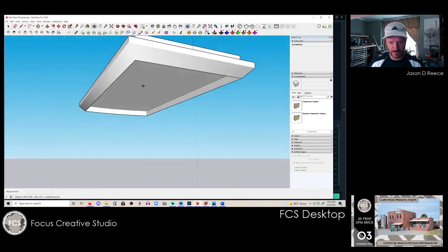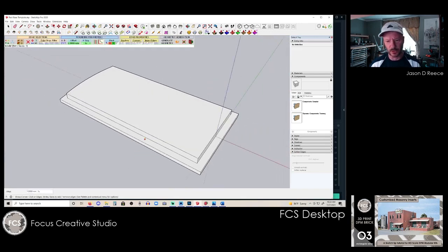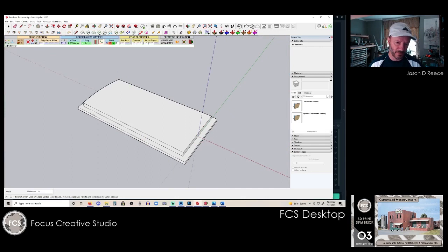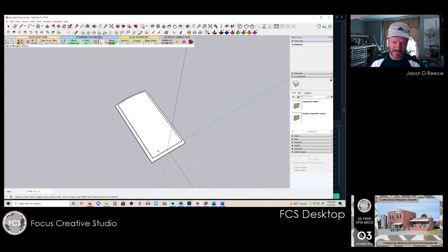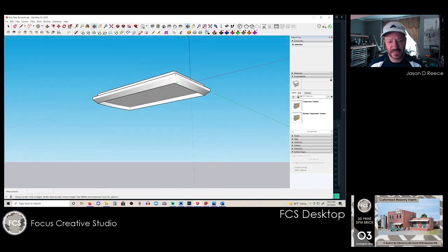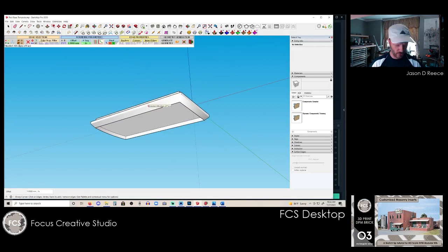So you learn some things when you dig through enough of these to try and make things as simple as possible for the modeler. So this is the bottom. The slight arch is at the top. And again, all these dimensions we're done with calipers right off the sample pieces that I have. So one of the things you want to think about when setting these up is how your model sits against the build plate, drains. Those things are important to remember at the beginning. Don't develop a model and say, oh, how am I going to support this? How's it going to print and drain when it's going through the process? I think that's what causes a lot of people hurdles, unfortunately.